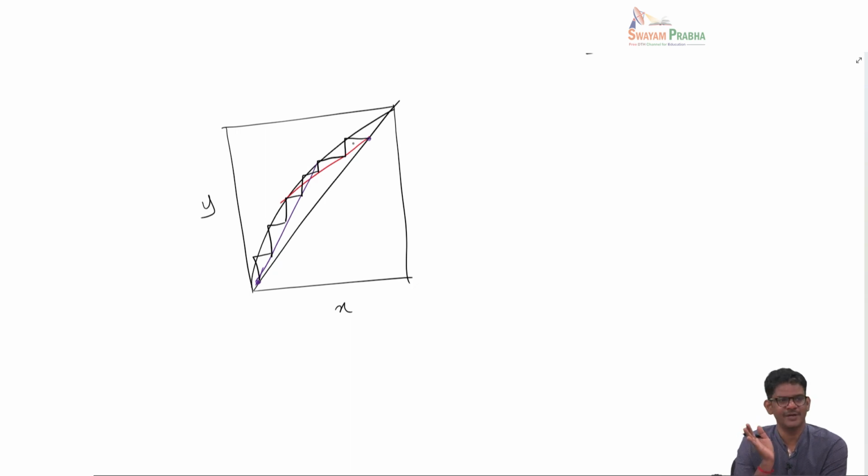The slope of the operating line also depends on the reflux ratio I am using, because the slope is proportional to the L/G ratio, the liquid to gas flow rate, which in turn is determined by the reflux. Depending upon the reflux ratio, the slope will change, and the intersection point between these two lines will also change. So there are a lot of interesting questions to be answered: how do I choose the reflux ratio?